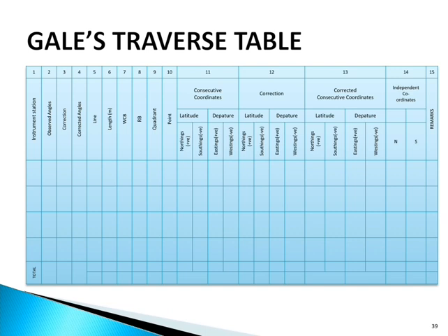Next, enter corrections in column 3. We have mentioned the correction to each and every angle. Next, write the corrected angle in column number 4. Starting from the observed bearing of the initial line, or say AB in this case, calculate the bearing of all other lines from the corrected angles.